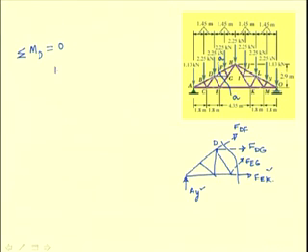So, that is equal to 1.5 times 2250, because we have some applied loads at these points, the 1.13 kilonewton force and the 2.25 kilonewton force at B, A and D. When we take the moment of all these forces about this point D, the moment of this force is 0, the moment of the 2.25 kilonewton force about D is 2250 times 1.5 meters, which is the moment arm,